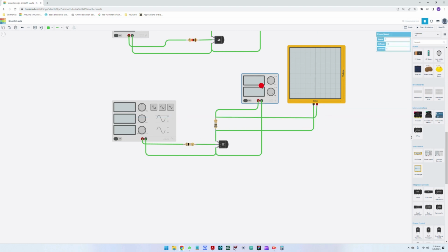Great. The power supply, maybe we can put even more, let's say 15 volts. Power supply, we have a 8 ohm resistance here, and we need a bigger resistance for the base. Let's put a 10 kilo ohm resistor for the base.